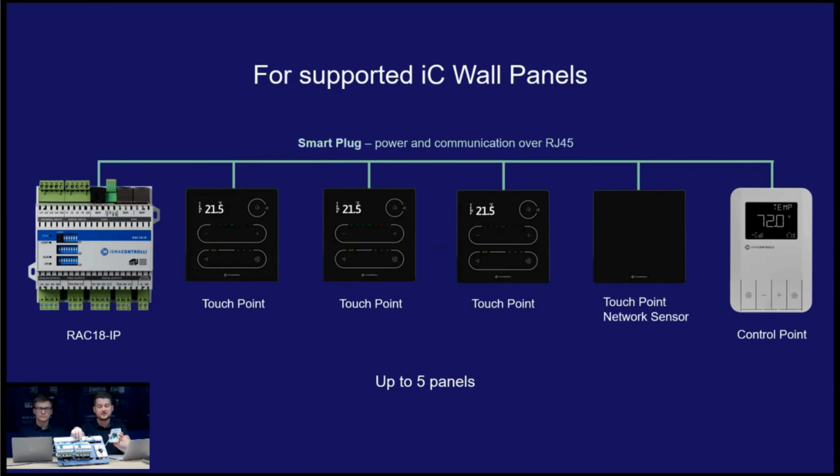So this is not IP connectivity, this is not PoE, this is actually our smart plug technology that powers up and shares the BACnet MSTP and Modbus RTU. So if we disconnect this cable here, that is directly connected to the RAC18, the panel will switch off. But once the cable is connected, it is powered and starts the communication directly with the controller. And it can go back on the wall.